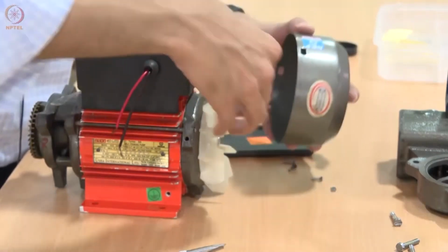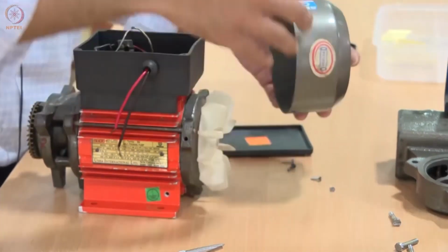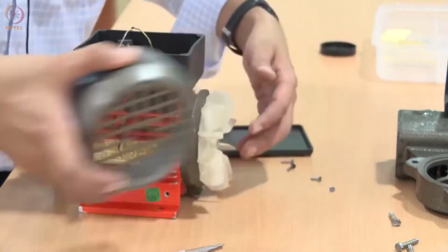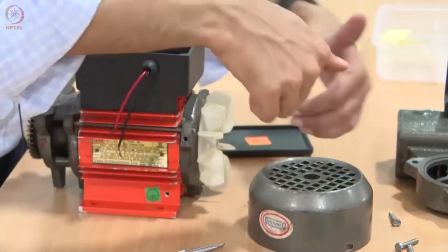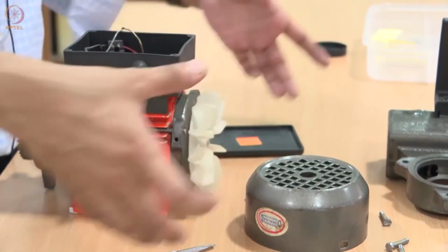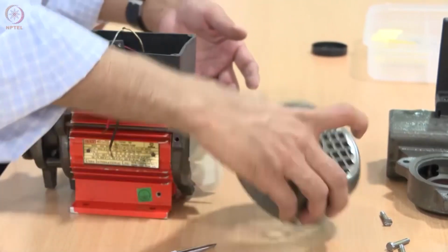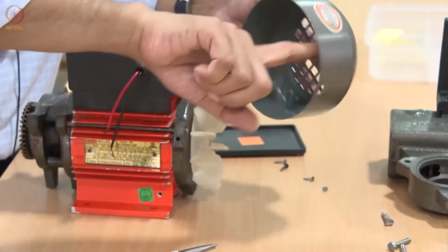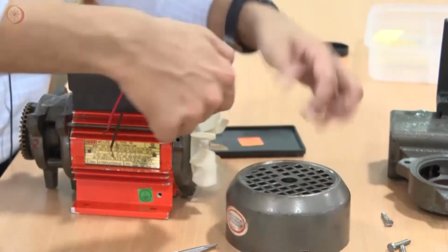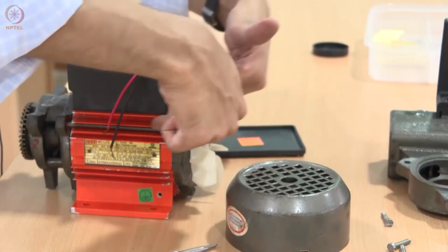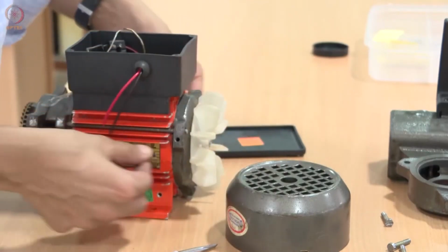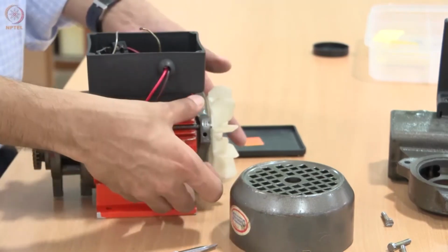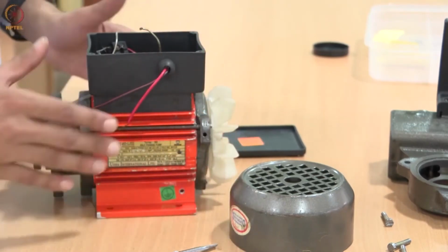So this is again a centrifugal fan. Air enters axially, right? If this casing were not there, what will happen? Air will enter axially and be blown out radially. Since I have a casing, what happens? Air enters axially, it is thrown out radially, and the casing will redirect the air back axially over these fins. So in operation, if you keep your hand here, you can feel the air flowing over the fins to cool the motor.